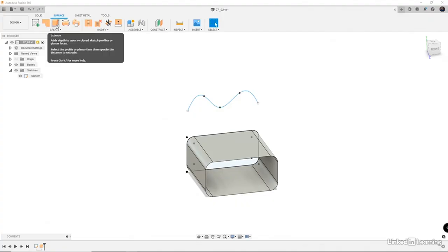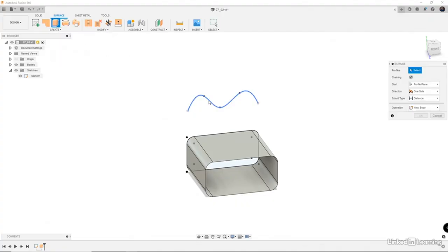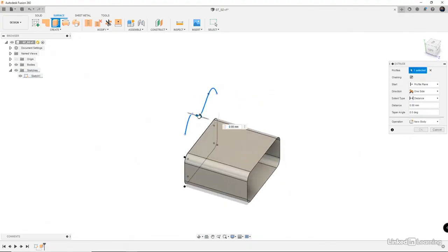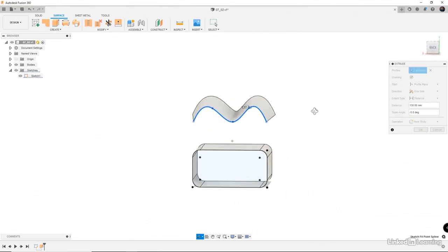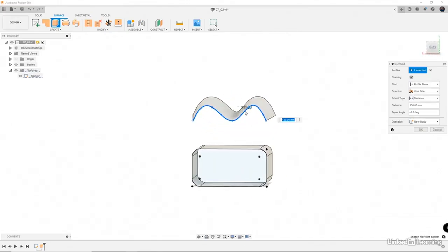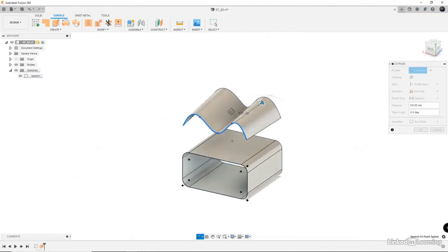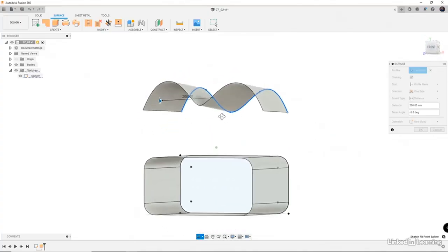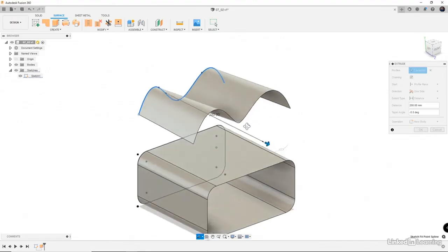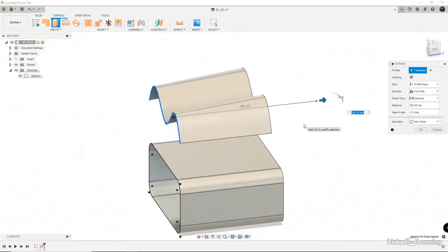And let's go to the extrude, and we can set this here, and we can do a cool surface and maybe put a little bit of a taper on it. It wouldn't do a positive taper because it would implode on itself. So I did a negative taper so that it gets bigger as it comes out. But yeah, this is a cool surface that we have that's driven from the spline, and we can use this to drive some other types of geometry, do some cool stuff. It's just a very helpful tool. So this is a great example of that.